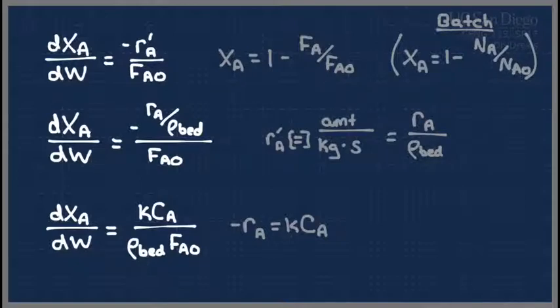The next step is the part that has subtly changed from a batch reactor, but not enough that it makes a terrible difference in the way the equations look. Was there a question over here? Thought I saw a hand up. Pavlovian response. So if we want to work on that CA, the CA that we need here follows a similar definition as what we had seen in the batch reactors, except it's FA over V. So that V, I'm not putting the caps on there. That V is the volumetric flow rate, V.